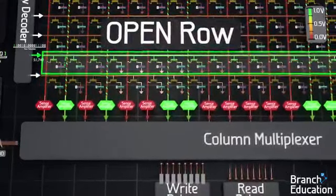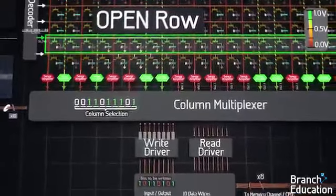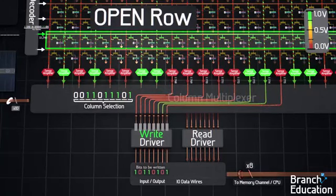Next, the column address goes to the multiplexer. But this time, because a write command was sent, the multiplexer connects the specific 8 bit lines to the write driver, which contains the 8 bits that the CPU had sent along the data wires and requested to write.